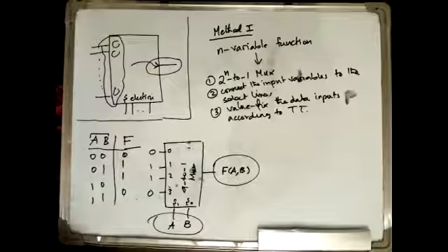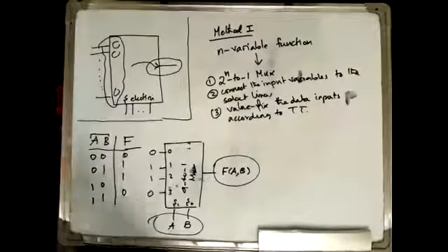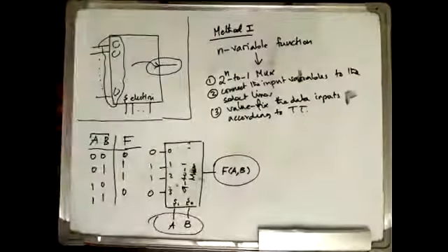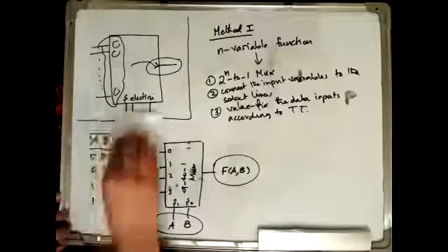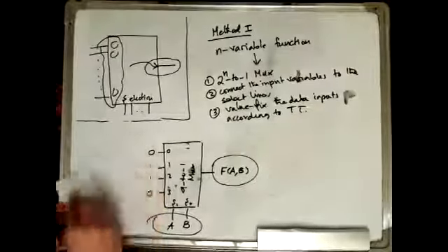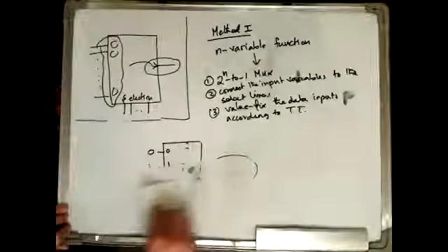And so on. So as the number of variables increases, the size of the multiplexer in terms of the number of inputs increases exponentially. And this will be expensive, despite the fact of being a straightforward and easy way to implement the functions. So the idea here: how can we reduce the size of the multiplexer, but at the same time still be able to implement the logic function?